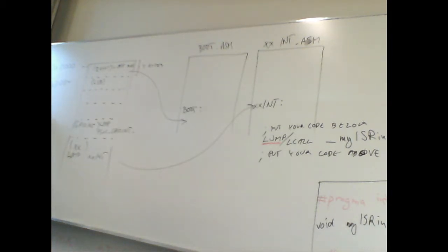But any other lower priority interrupt has an enable GPIOINT, or something like that. There are actually routines that enable exactly that interrupt. And in addition to that, of course, you must have the enable global interrupts.